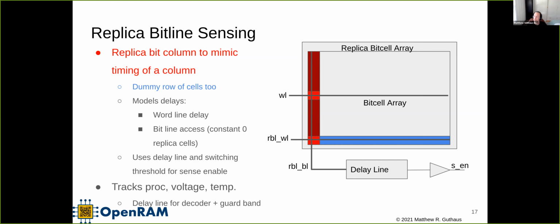Yes. I think Sky 130 uses a little different trigger. I think it's a falling edge, right? Or I don't know what you mean by Sky 130. The memories? So yeah, the design OpenRAM generated, and somebody should correct me who played with that if I'm not correct. I think it starts decode on the rising edge and fires the sense amp on the falling edge. So yeah, you're actually kind of correct. It does the pre-charge during the high phase of the clock, and then it does the access on the negative edge. Yeah. So this all happens on the negative edge. Okay, all right, thanks.